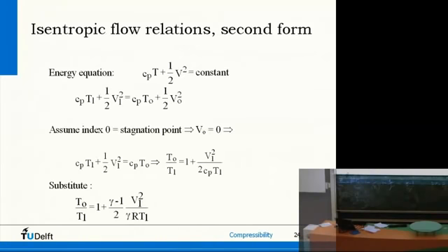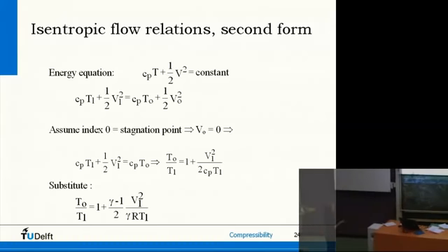So this Cp here, I'm going to replace by gamma R divided by gamma minus 1. But of course I have to divide over it, so the gamma R turns up here, gamma minus 1 there. So reworking this pressure specific heat coefficient, I get to this version.